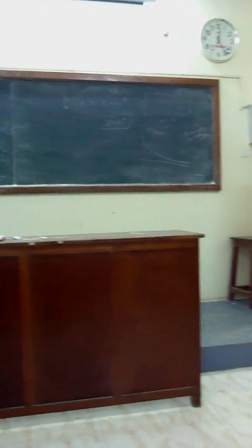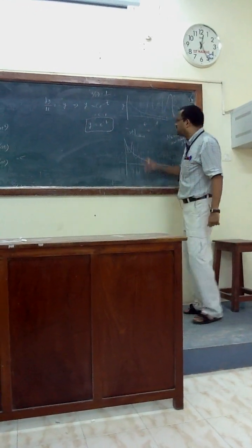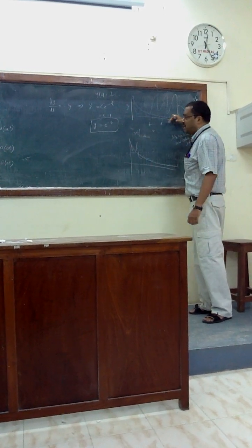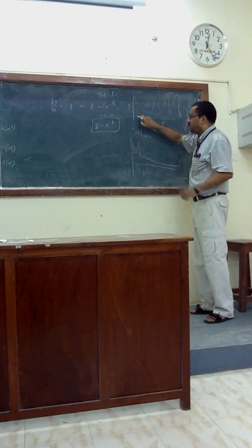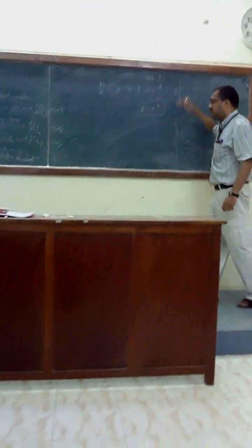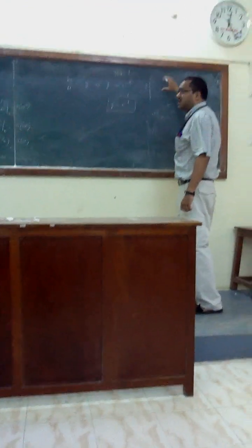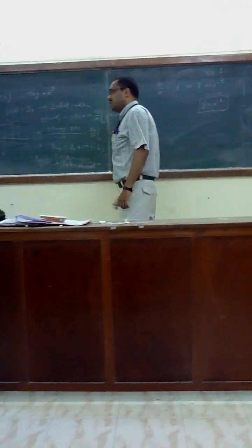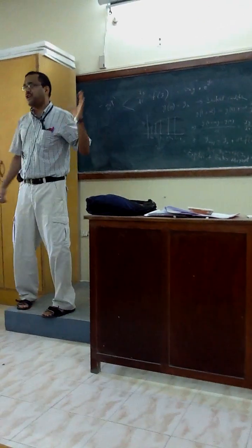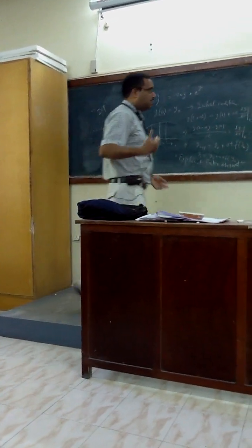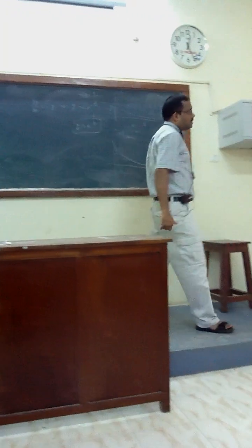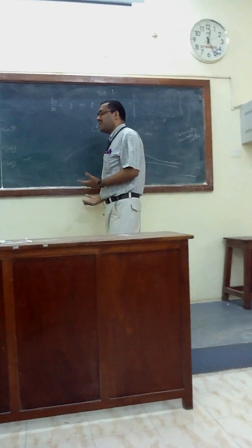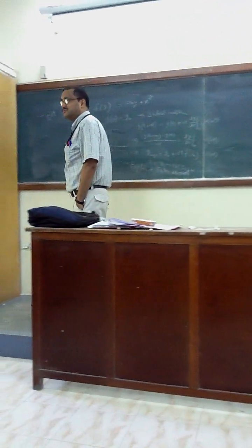And there is some special delta t, critical delta t. My point is that here the gradient is very high. At this point you have very small delta t. Beyond that point you can have a much bigger delta t, no problem. But here if you have bigger delta t, you can get huge numerical oscillation, and once oscillation is there, it will not die out. It will propagate, and you will get much error. This is a very good experiment. You can go to your computer, do the MATLAB simulation, and see how a simple problem like this can lead to numerical oscillation and a numerically unstable solution.